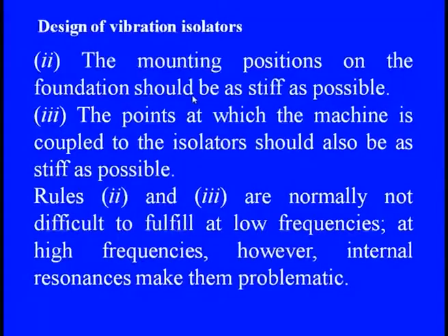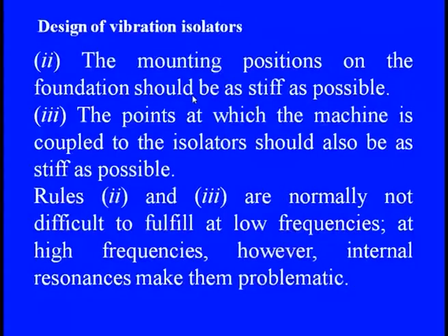Second, the mounting position on the foundation should be as stiff as we can provide, because if the mounting position is less stiff, it gives a flexible foundation and then the excitations will be significant. Third, in the design of the isolator, the point at which the machine is coupled with the isolator should also be as stiff as we can provide.